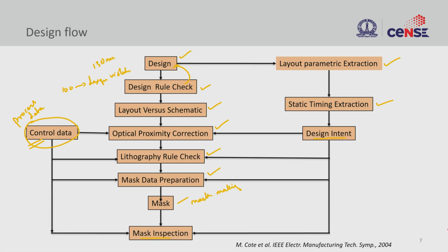So if there are any defects, then what we do is this again. So these defects could be corrected. There are two types of defects again. One is a random defect that could happen because of process variation or some process failure during mask fabrication, or this could be from data preparation itself. So if the data prep was not clear, and if you are getting some systematic failure in your mask writing, then you go back to your mask data preparation, and you fix that problem before making the mask. And once all of this is done, then you take the mask out for further fabrication.